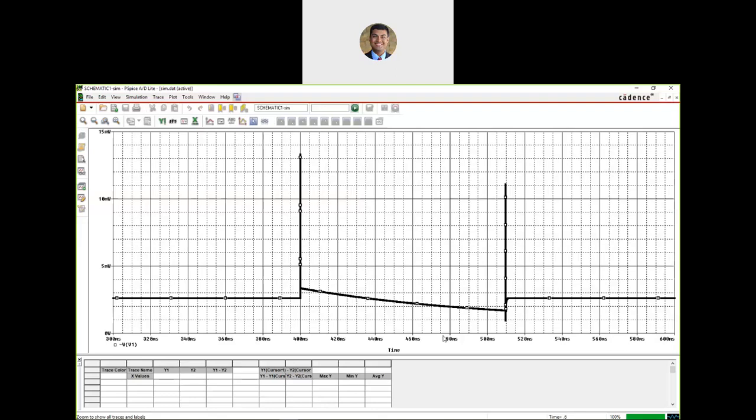I hope I have given you a good idea about how to monitor average power consumption in PSpice very quickly. Just start up a simulation profile and add a trace which monitors power of the supply voltage. Note that this is not going to be for all those V pulse bouncy switch related voltage supplies. This is only going to be for the DC power supply, the power supply of the entire design. We are trying to monitor the power for that. And in my case it was V1.